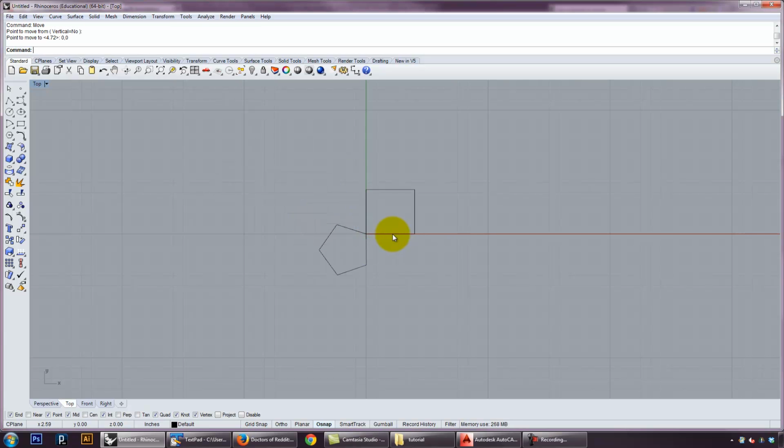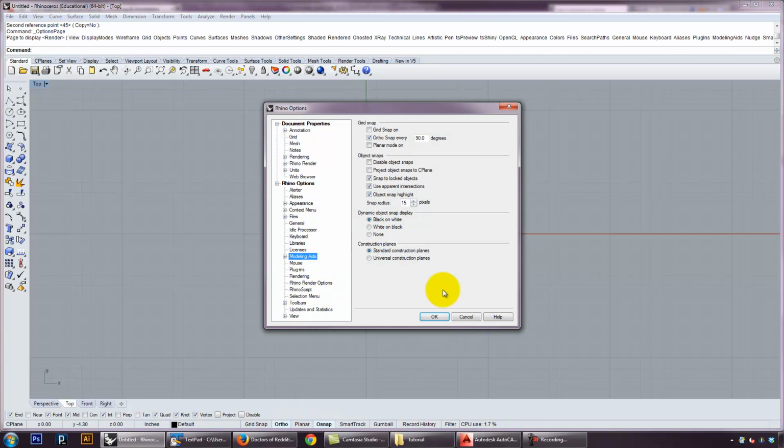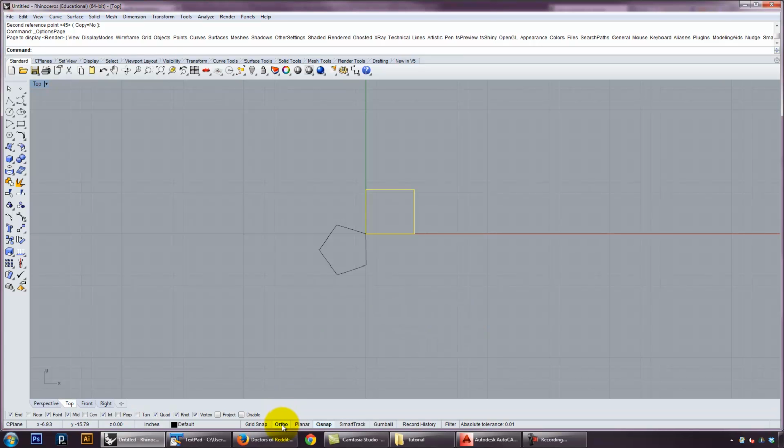Okay. The other command is rotate. So I can rotate an object, and you can specify an angle. So I can say rotate this 45 degrees, or I could say rotate, and I'm going to make this my reference angle, and I can rotate by sight. You can use the orthographic snaps as you did in AutoCAD to get a constraint to 90 degrees. You can also do polar constraints. You can change the angle. There aren't polar snaps the way that there are in AutoCAD, but you can change the ortho angle to be anything, so 15 degrees or something if you like.